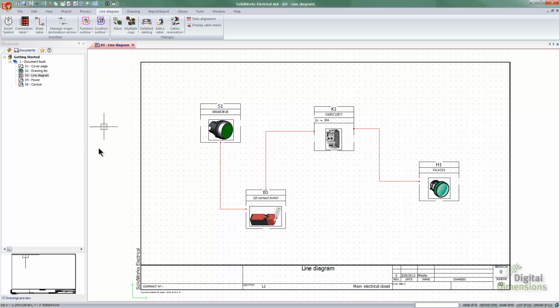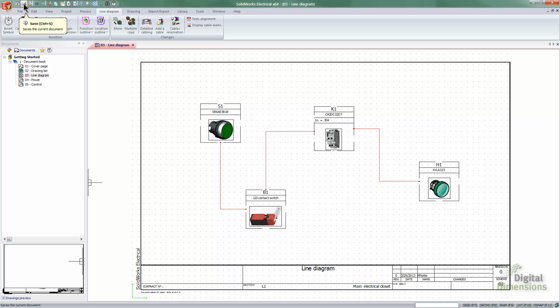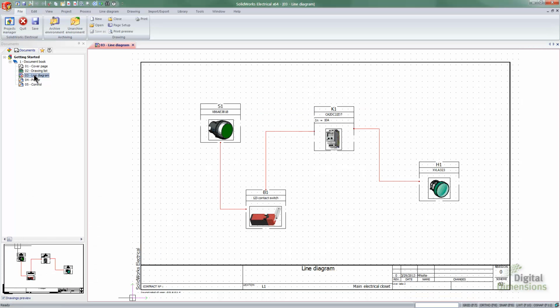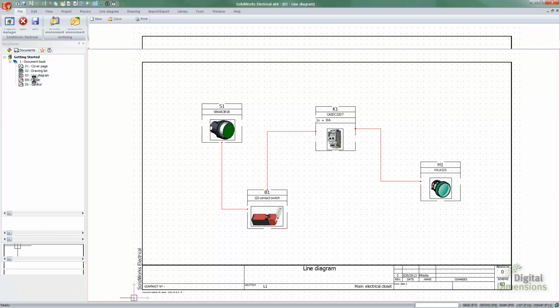Multi-line allows us to go through and get the specific information in there. Oh, you might have noticed that the preview isn't showing up. Well, I can either save the document, or SOLIDWORKS Electrical also automatically stores all the information. So if I close out of the single line and then come back to the single line, you'll see that the preview updates. So you don't necessarily need to save the document. It automatically saves for you. Double click on it and you'll be able to see the full drawing there again. So we'll leave that open for the time being here.